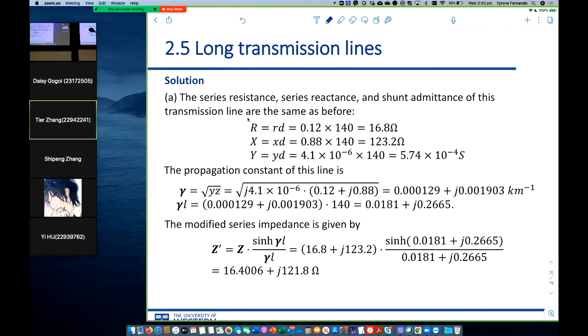That is a complex number, because y is the admittance of the capacitor, so it's j times some value. Because 1 over j omega C is the impedance, admittance is the inverse of that. That's why the j term is in the numerator.